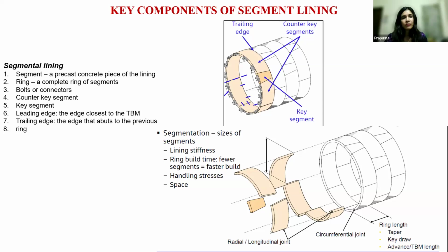Hyperbaric intervention was a very interesting question asked in Dubai Metro by one of my colleagues. But in Dubai or in Riyadh we have sandstone, we do not have very soft ground conditions, and the groundwater is also very low. If you work in Saudi, in the Middle East regions, we do not encounter very high groundwater scenarios. So there we do not need hyperbaric intervention.